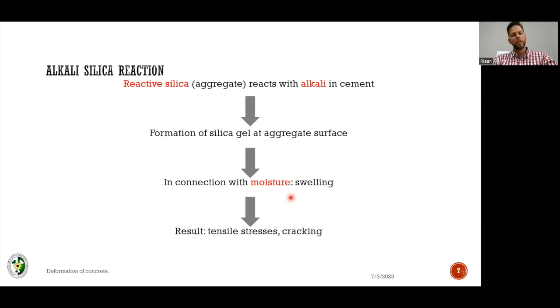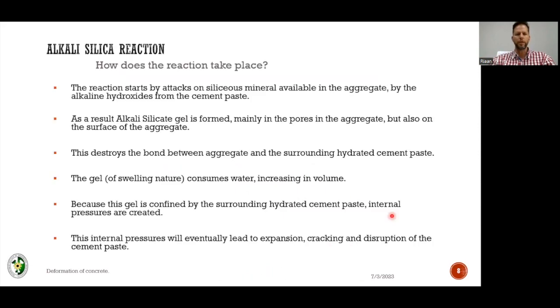If you can imagine a massive piece of concrete, a bridge base, if it's underground, you cannot remove water in there. You cannot. The water will be there. There's no way of sealing it. But generally, stuff that's in the ground doesn't fall on people that are driving below it. It's the stuff that's suspended in the air that falls down on people. So if you want to prevent the first floor becoming the ground floor, this is what they were doing. They were sealing those bridges to prevent further moisture ingress, which would then fuel this whole ASR process.